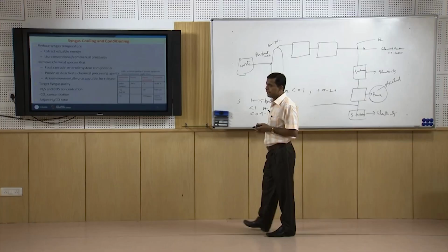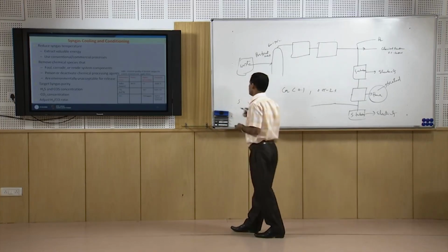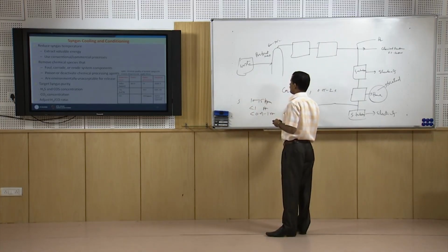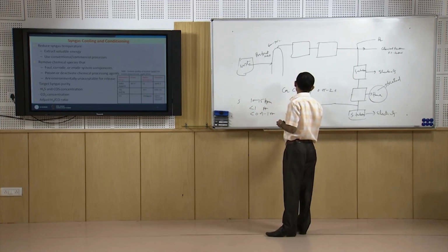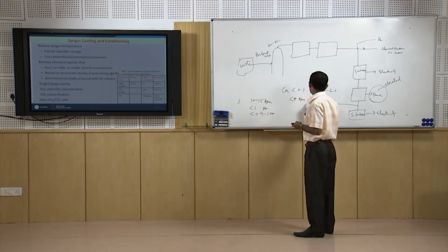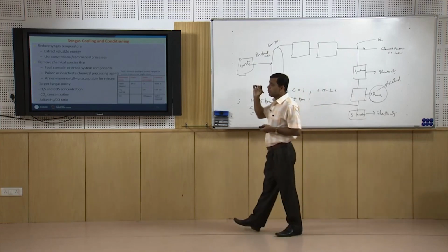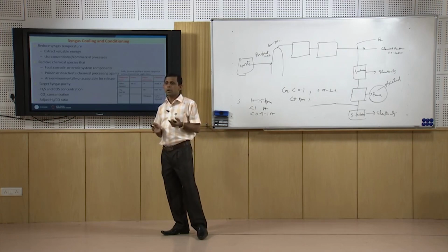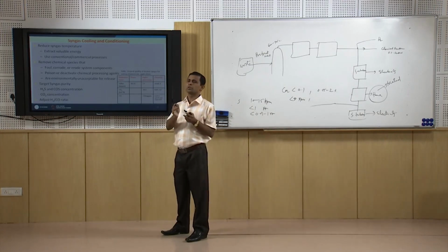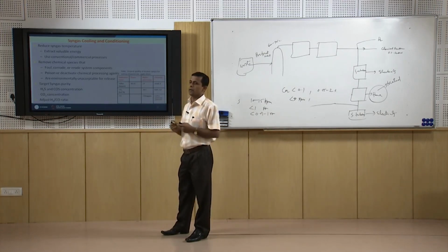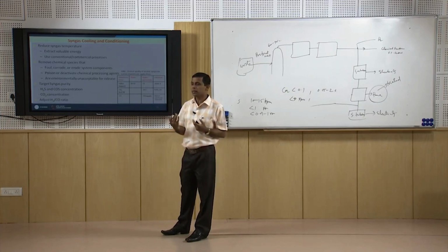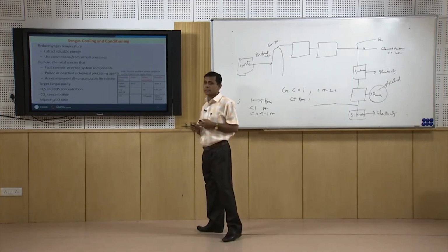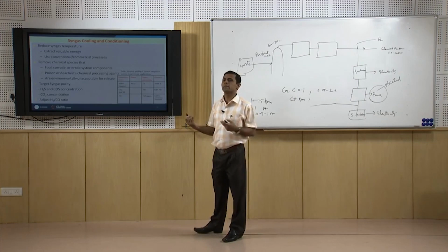For carbon monoxide, for hydroprocessing it is less than 50 ppm on a weight basis, and for chemical synthesis the CO will depend upon the process, because different processes require different H2:CO ratios in the syngas. Somewhere it is required to be 2:1, like Fischer-Tropsch synthesis, somewhere 1:1, like DME synthesis.